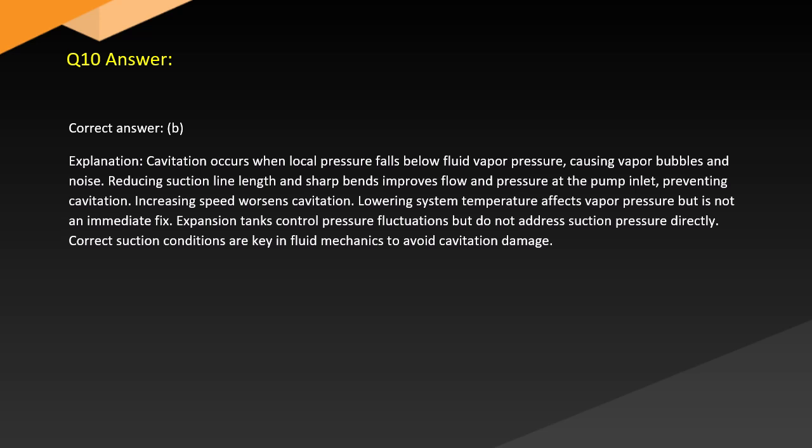Increasing speed worsens cavitation. Lowering system temperature affects vapor pressure but is not an immediate fix. Expansion tanks control pressure fluctuations but do not address suction pressure directly. Correct. Suction conditions are key in fluid mechanics to avoid cavitation damage.